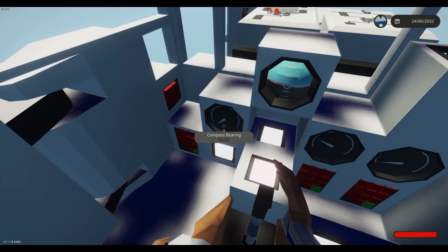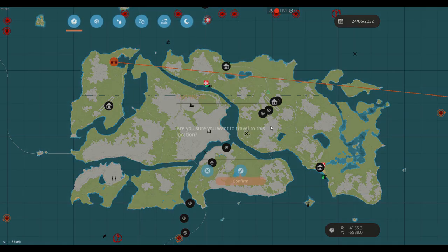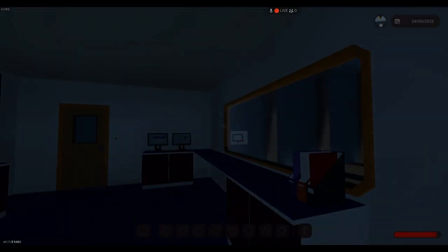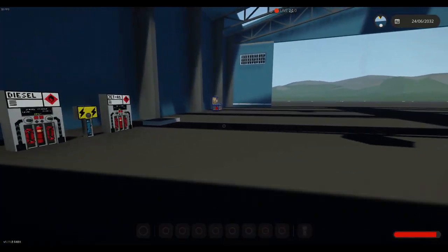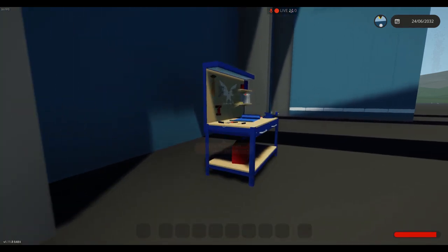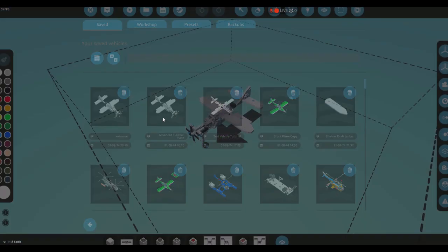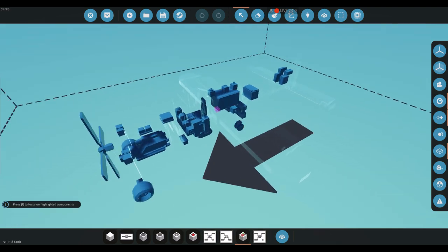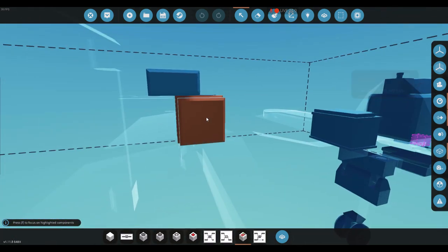And so we'll just auto-correct it. We'll just try and get it at 90 exactly using the rudder. And we'll see what the PID does a little bit to the right. We'll see what the PID does here. So it looks like my proportional value just needs to be stronger, so we'll take care of that now. What I had there wasn't a complete failure. It still worked for the most part. It was just slightly inaccurate. So we will come to the PID.